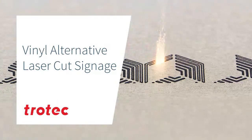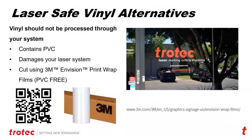Another common question is vinyl signs. Vinyl is a very popular signage material, but it contains PVC, polyvinyl chloride. Polyvinyl chloride or PVC-based products are bad for your laser system. If you don't know already, vinyl can actually produce chlorine gas when laser cut, and it is very corrosive. And that corrosive nature will actually damage your laser system. It'll literally eat metal right out. The component of the chlorine will actually eat metal away over time.